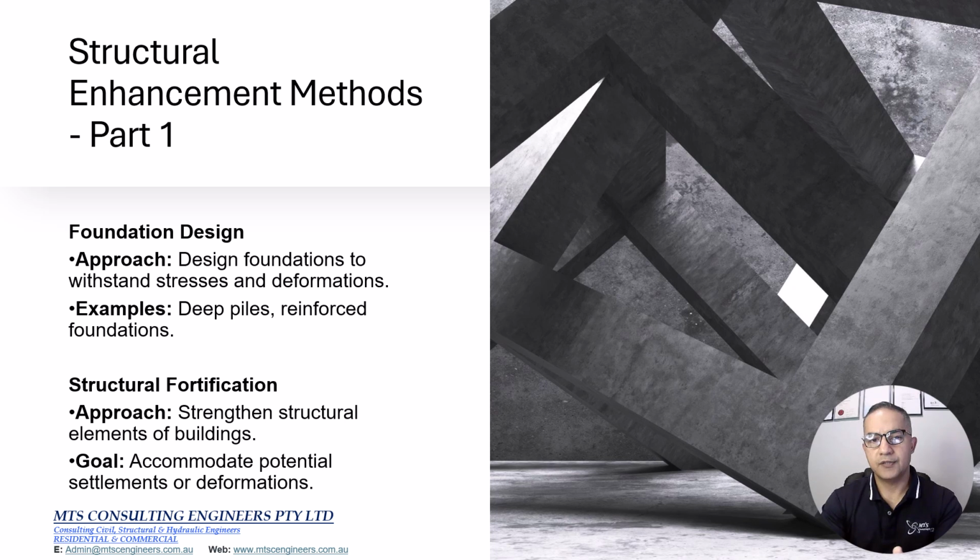Now, let's shift our focus to the structural enhancement methods. One key aspect is foundation design. The approach here is to design foundations that can specifically withstand the stress and deformation caused by liquefaction. Examples include using deep piles or specially reinforced foundations.